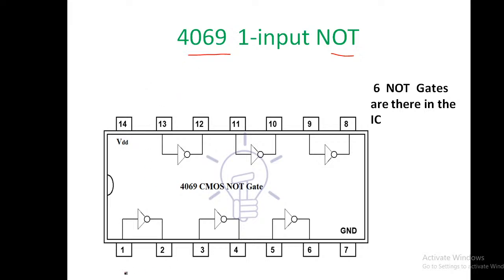One thing I also missed telling you, because it's not a hardware lab. When you are putting this in the breadboard, you have used breadboard and circuit diagram also. For implementation purposes, when you are counting the IC pin numbers, you just find the notch and put the IC in this way and number the pins, because in the real scenario no numbers will be given, right?